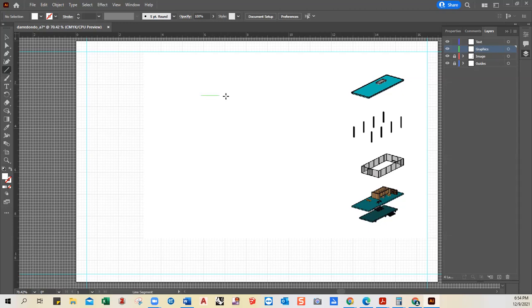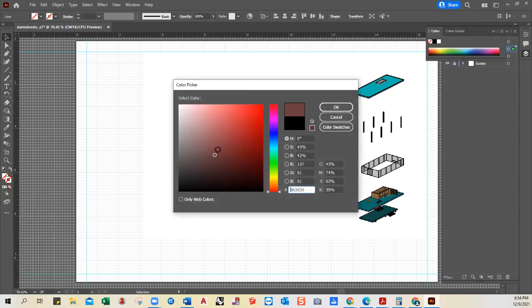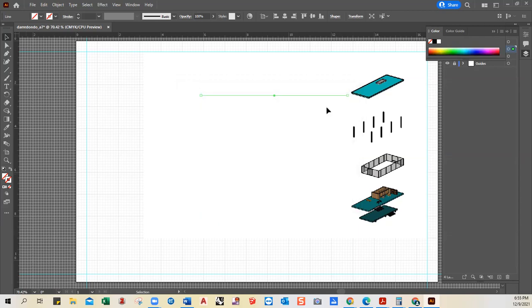And I'm going to go ahead and draw lines. Now, right now, it looks like I have a line there, right? But if I deselect, it disappears. Why? Well, notice how over here, when it comes to color, the stroke and the fill are blank. I'm going to have to add a color there. So the stroke is the outline, the fill is on the inside. So the stroke here, if I double click, I can choose a color, right, of my liking, any color here. I'm just going to choose black, hit OK.